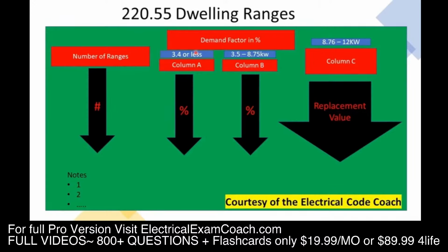Starting on the left-hand side in column A, this is when your individual range falls 3.4 or less kW. In column B is when the individual range itself falls in between 3.5 and 8.75. Then column C is when our ranges are 8.76 through 12 kW. Then in the bottom left hand of the table, you're going to see some notes. That's when we have a situation that doesn't fit into the normal table, and we're going to take it piece by piece. Let's get to it.